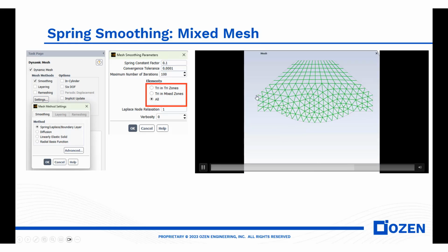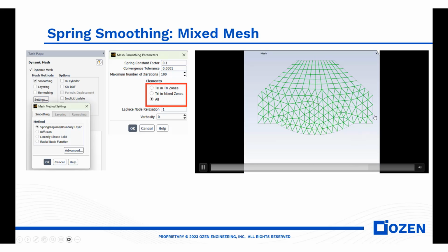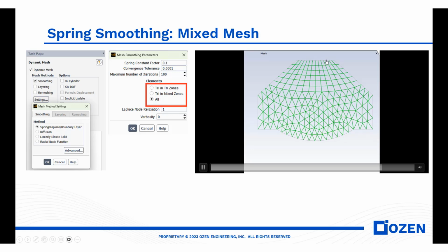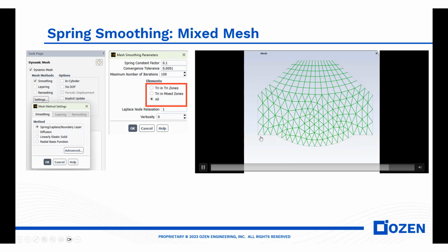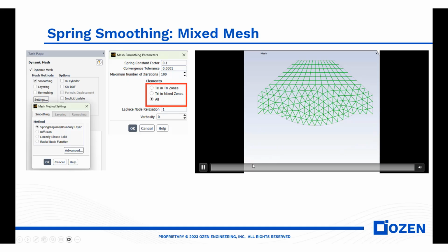So this wall and this wall should be deforming zones, but on top we can define stationary. And at the bottom, the moving wall should be a rigid body motion, and so we need either a profile or a UDF to define this vertical motion for the moving wall.